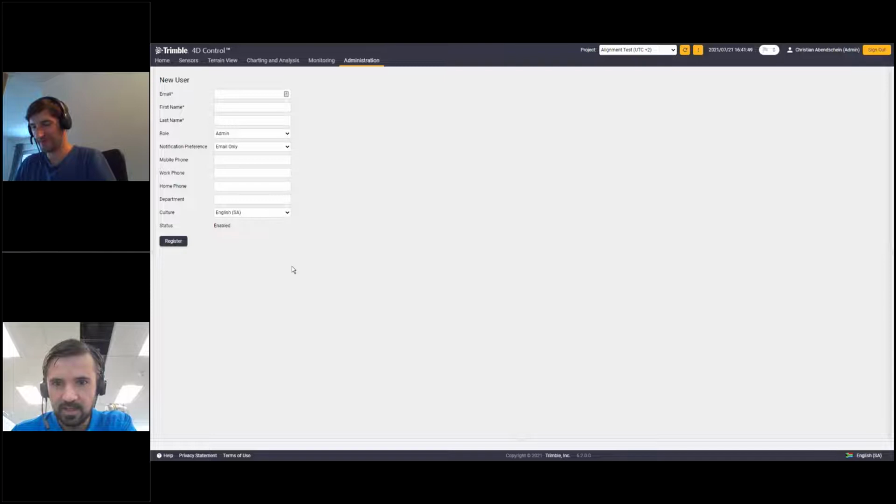Another question, asked by Ruli, was: can the alarm definitions you're showing in T4D be set up to sound an audible alarm or a siren? Yes, you can also run a batch file. So if an alarm is triggered, you can run a batch file, and the batch file in turn can trigger a siren, for example. That's possible, and we also have some installations doing that.